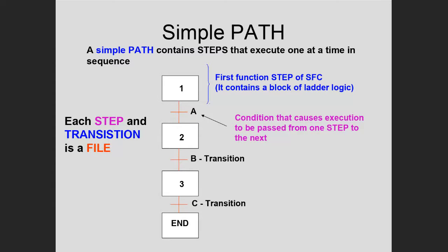And you can see how this works. You would run the program and you would run the code in step 1, whatever that is. Step 1 probably just does a few things. Maybe moves the conveyor up and clamps the part down. And then you have to have code to say when it's okay to go from this step to the next step. Well, that's what your transition does.